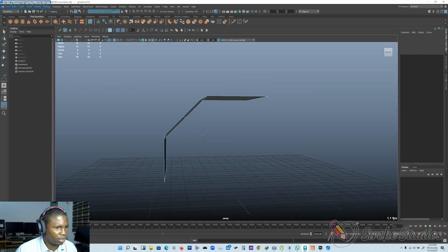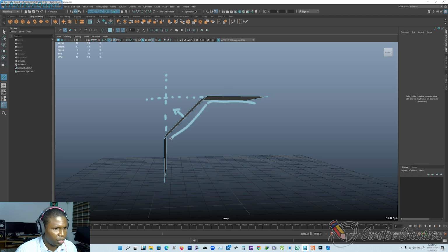This edge is going up this way, while this is going out this way, and I want this edge to pull up a bit, so that instead of having this straight side, it comes out this way but not all the way straight. It goes up to this point and up to this point, and it goes all the way down. To achieve this, I need to apply an edge flow to maintain a certain flow around this end.